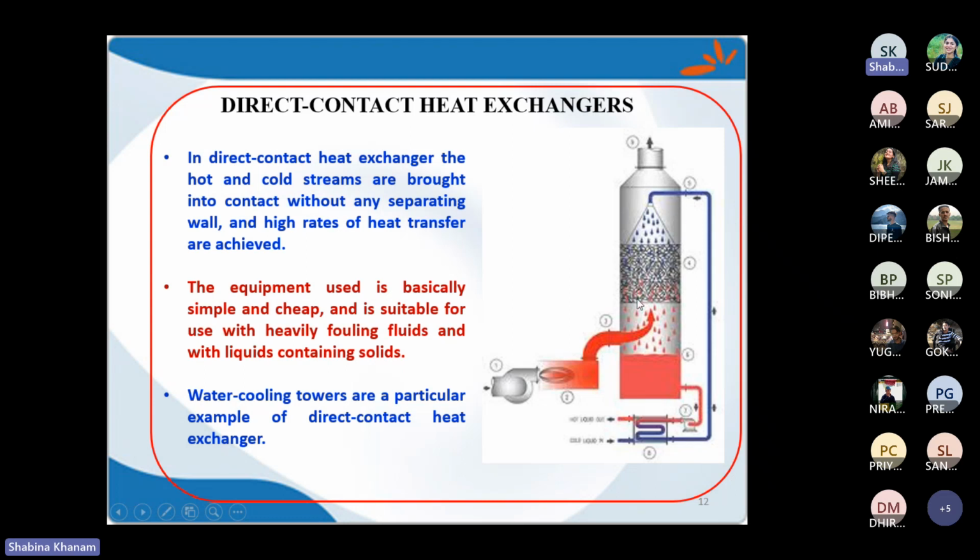So that liquid will be sprayed over from the top, and heat transfer will occur over here. So colder gas will leave this setup from the top. However, the hotter liquid will be assembled at the bottom, and then it enters into this heat exchanger, where the temperature of this hot liquid we again need to bring to the normal or cold temperature.